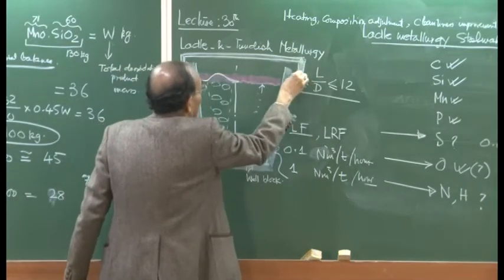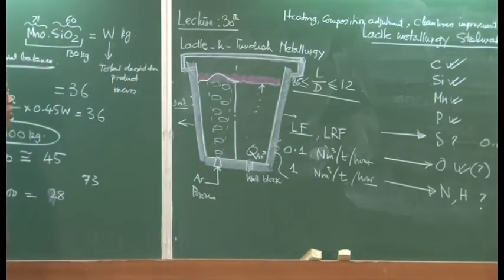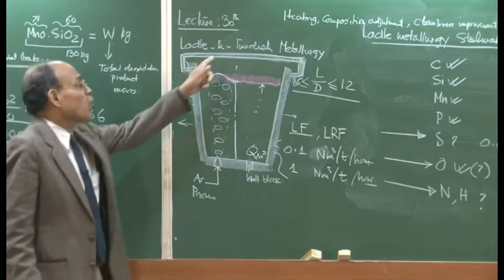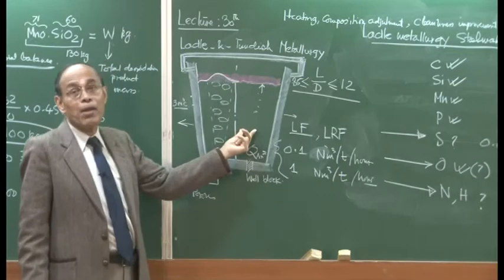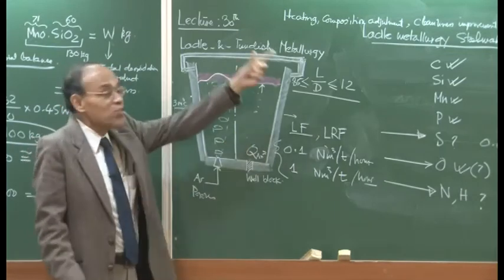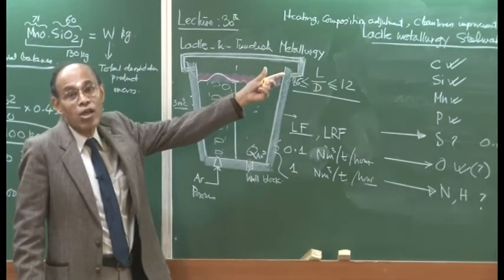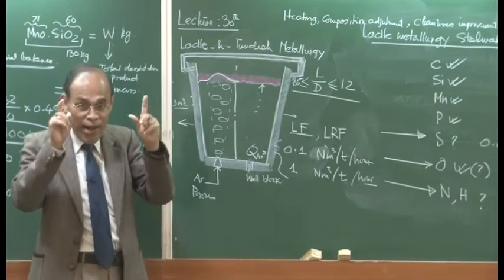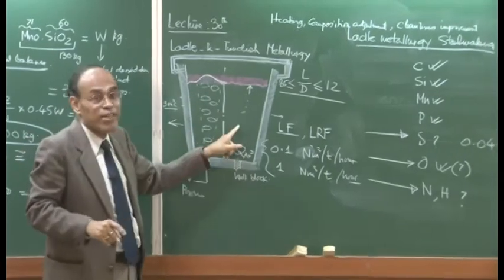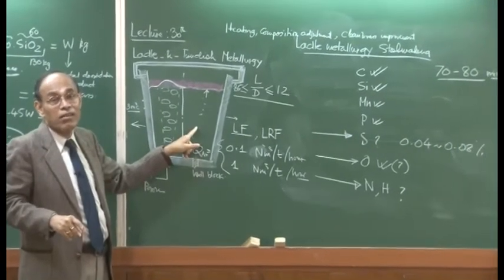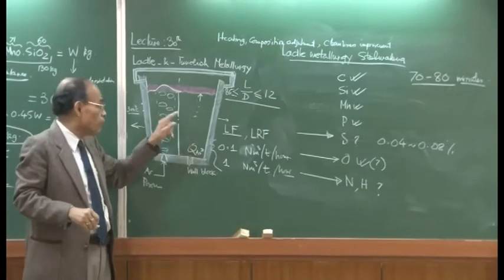So, this cuts off the atmospheric. So, as a result of which what happens? Heat loss, reoxidation. Reoxidation means, because now you have 10 ppm oxygen sitting here and outside PO2 is equal to 0.21, there is oxygen waiting outside, at the first opportunity itself it will try to get into the metal, which has great affinity for oxygen.